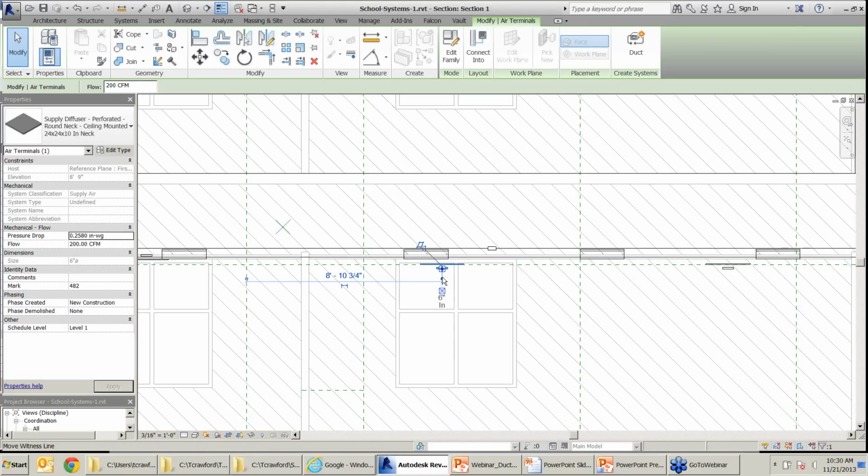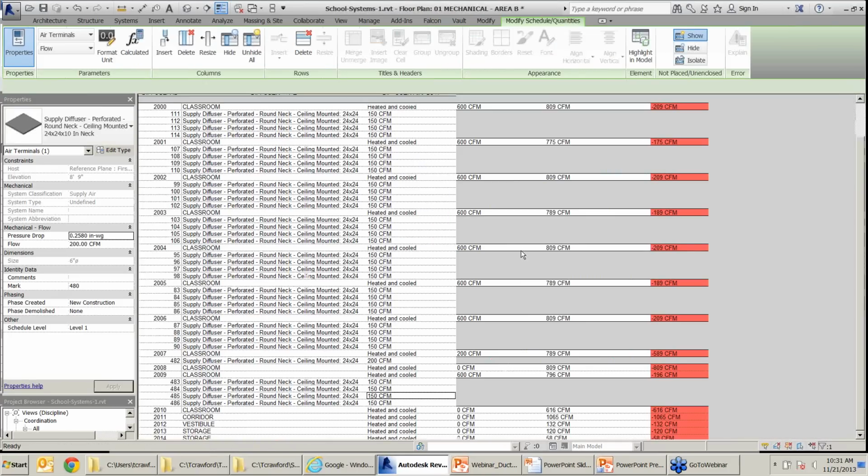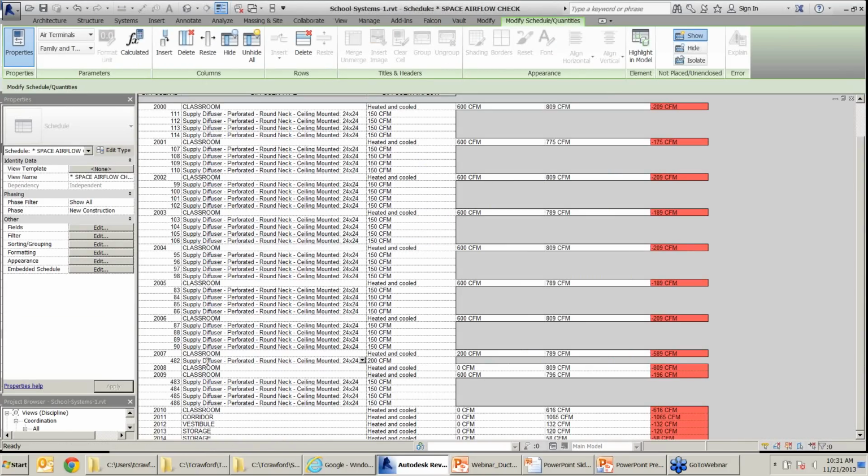I've got grips. Let's give that a try, actually. Room 2000. So, oh, well, that's silly. My air terminals are upside down. That was what was causing the problem with me. The airflow would have been read in the plenum space instead of in the room space. So that's what I get for getting in a hurry.